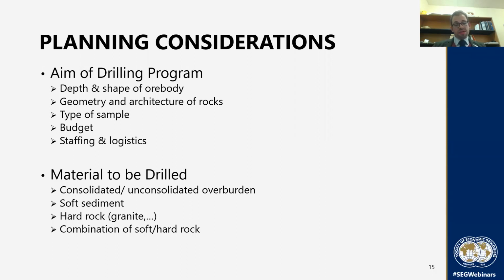Geologists should also be thinking about the actual material that's to be drilled, because that can have implications on the drilling techniques again. For example, are you drilling consolidated or unconsolidated overburden? For example, are you conducting soil drilling, and is that your main target, or are you interested in hard rock targets, or are you actually interested in a combination of all of the previous options?